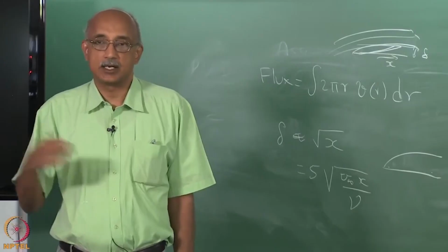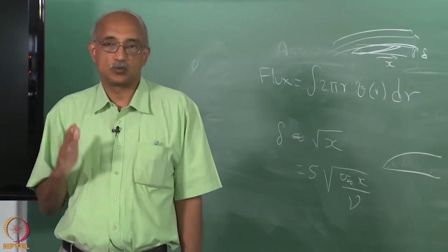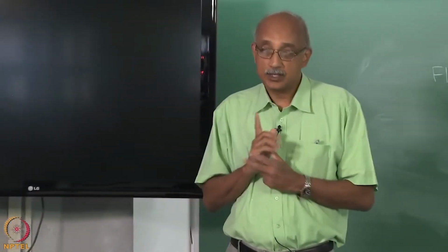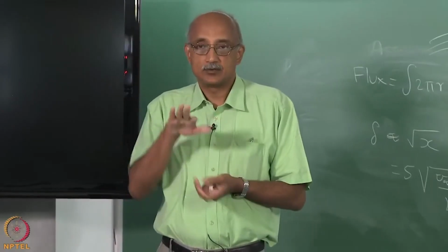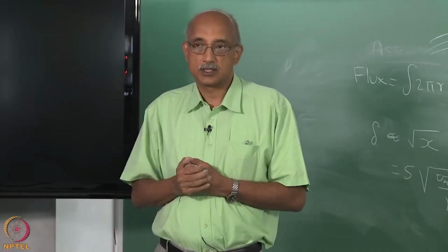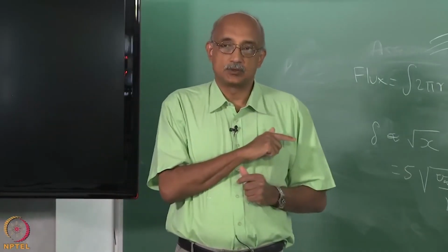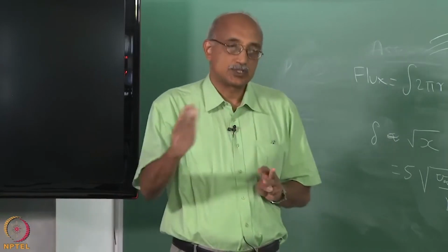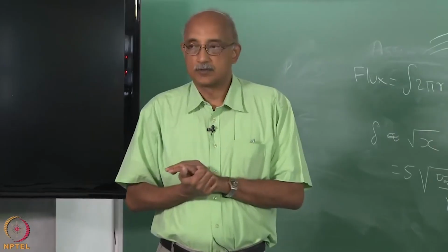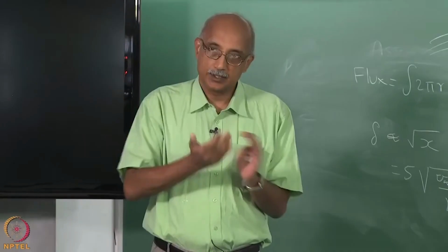So, instead of feeding in SiH4 at 100% concentration, you feed in SiH4 at 1% concentration with 99% hydrogen as diluent, and that only keeps the free stream concentration of silane constant across the length of the substrate. But it still does not address this issue that towards the trailing edge of the substrate you are going to have a drop off in the diffusional deposition rate compared to the leading edge of the substrate.